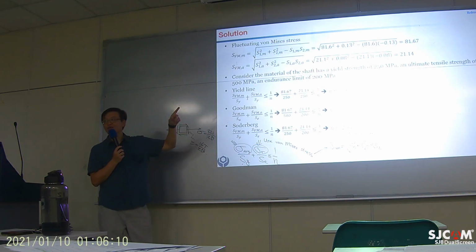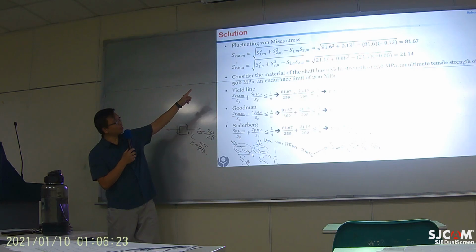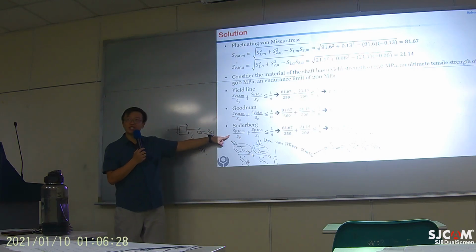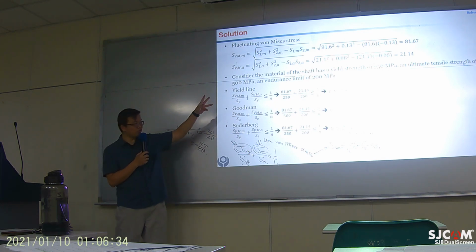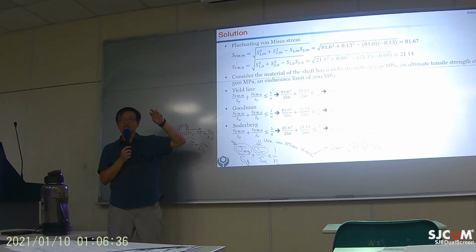I know it's at the end, well, I'm out of time. So please go back and take a look at this part. The reason why we determine von Mises stress is because for this model, there is no shear stress term. So you need to use the von Mises stress equation to cover stresses occurring everywhere.